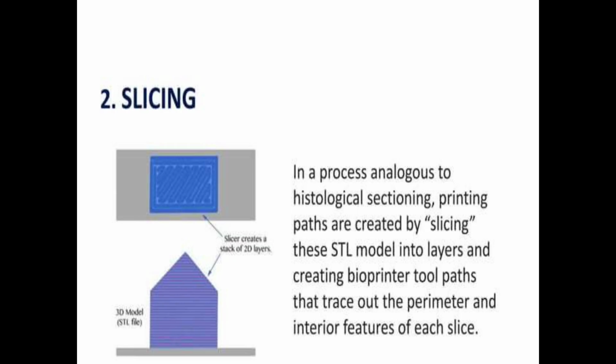And further we develop slicing techniques. It's a process analogous to histological sectioning. As we cut the tissue, we get layers just like a slice. In the same manner, the printing paths are created by slicing these STL models into layers and creating bioprinting tool paths that trace out the perimeter and interior features of each and every slice. We prepare layer by layer for the process of printing in this case.